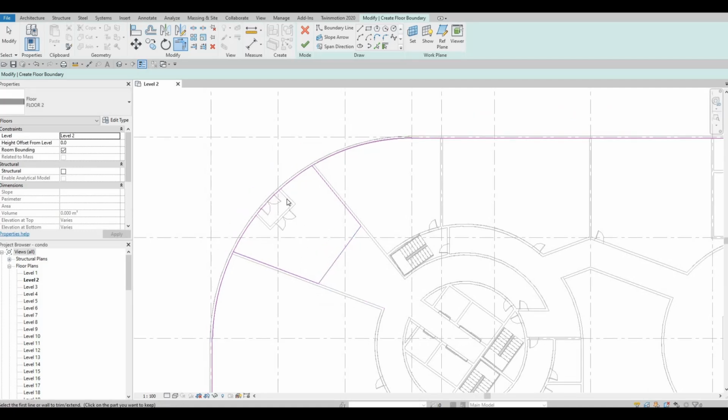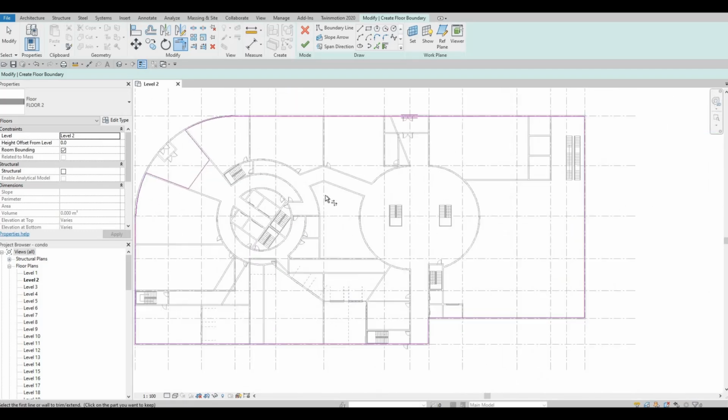And then now press escape, SL, that's split element, under modify, which is this icon. Click it there in the middle, press escape, TR, trim and extend. So now we have an opening there.